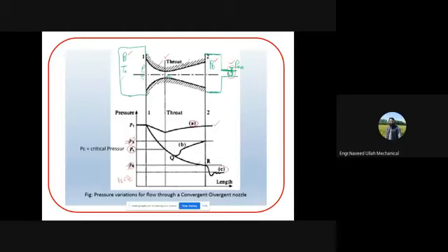Here you have your PC, but since it wants to be equal to this PR at the back pressure, it further expands but outside the nozzle. Remember, this expansion outside the nozzle is not of any work for us, it cannot give us any benefit. Because if the expansion is inside the duct, then you can attain the required velocity or required mass flow rate, okay.